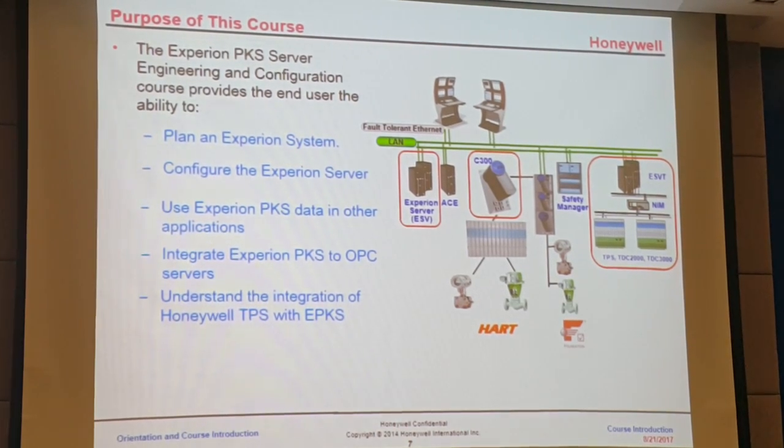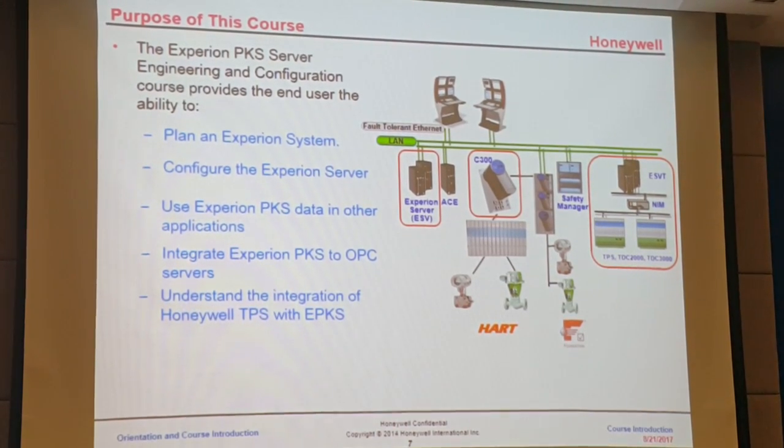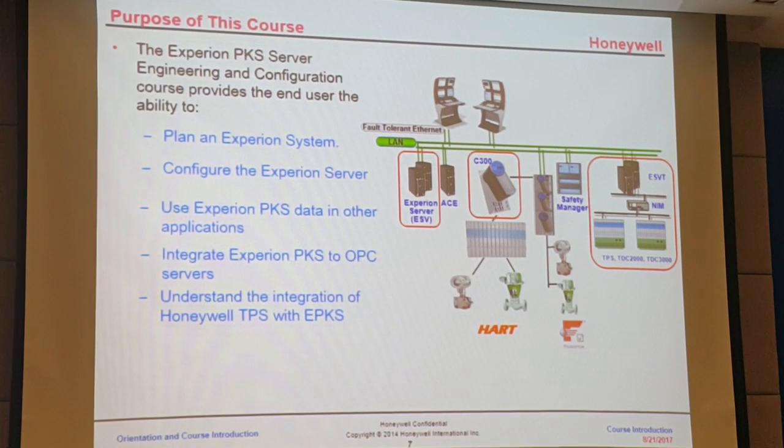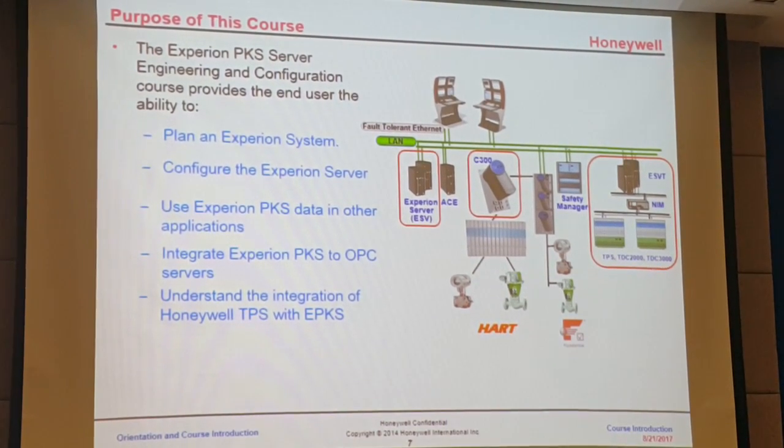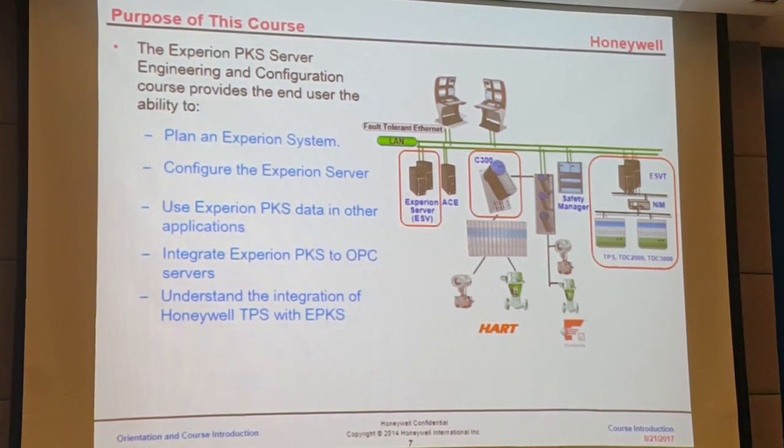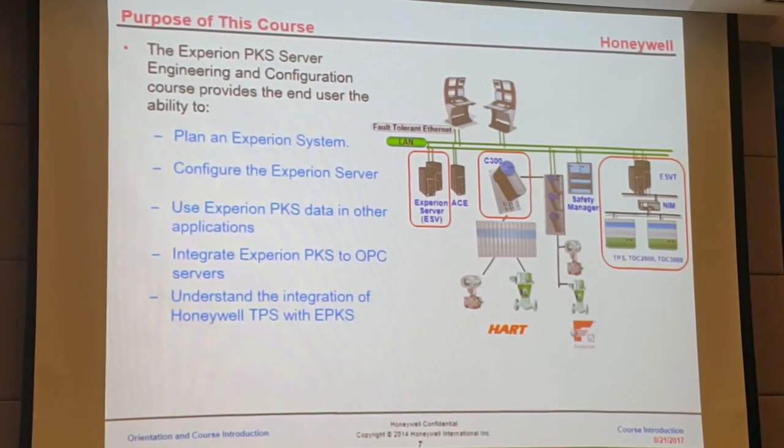There is the process controller, either C300 or C200. We call them process controllers, and there are all other controllers made by various manufacturers, not from Honeywell. We call them SCADA controllers. We are going to concentrate in this course on setting up a connection to a SCADA controller.